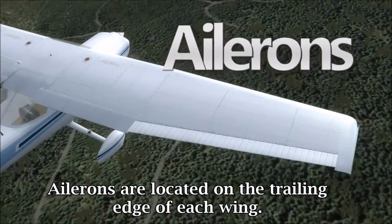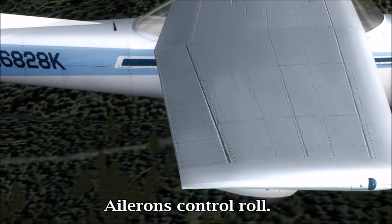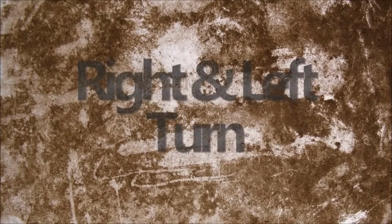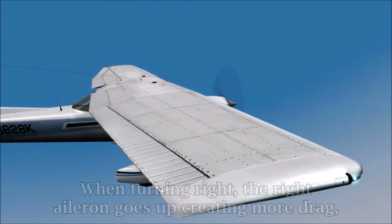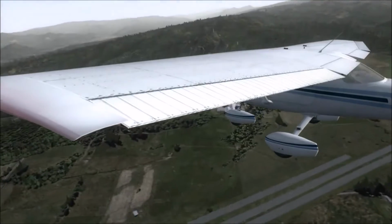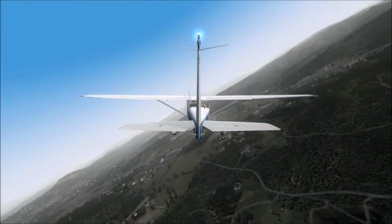Ailerons are located on the trailing edge of each wing, usually toward the outer edge. The ailerons control roll. Roll is what gets us to turn. Let's check this out in a right turn and a left turn. When turning right, the right aileron goes up, creating more drag, while the left aileron goes down, creating more lift. Therefore, the right wing dips and the left wing lifts. We are now in a turn.